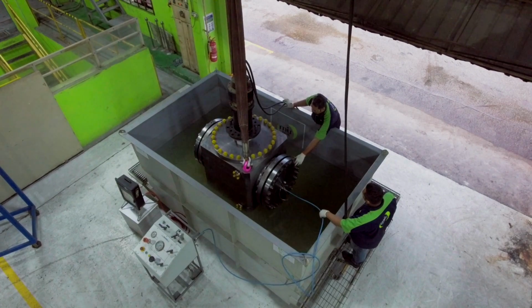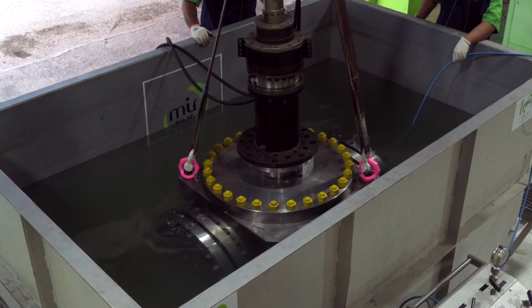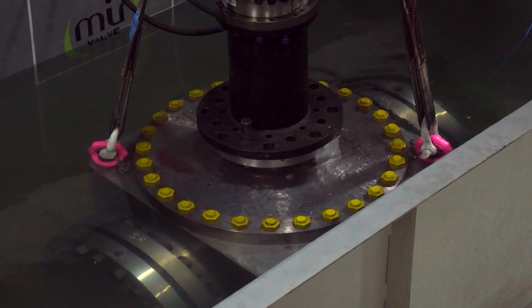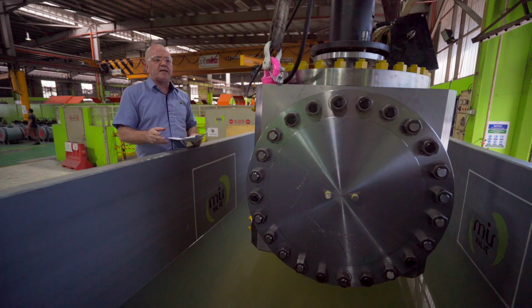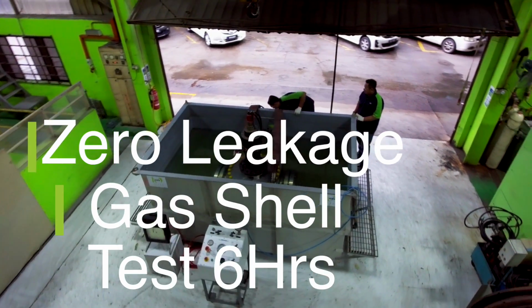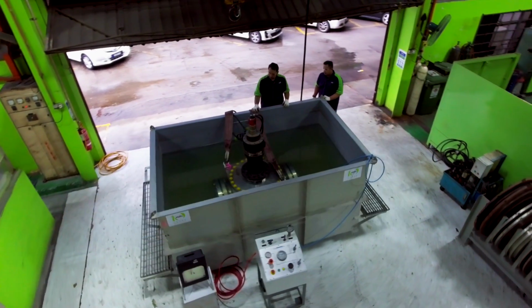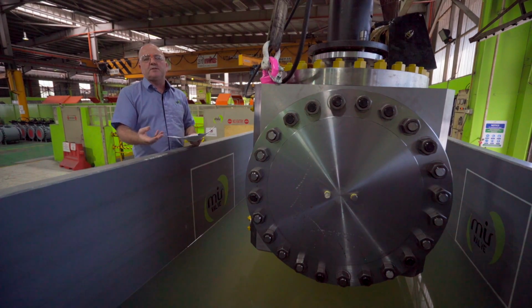We will then introduce nitrogen gas at a pressure of 57 bar or 825 psi. The pressure must be held for 6 hours, and during the 6 hours no bubbles are allowed to come from any part of the valve or any of the fittings attached to the valve. If any bubbles are seen, the test will need to be repeated.